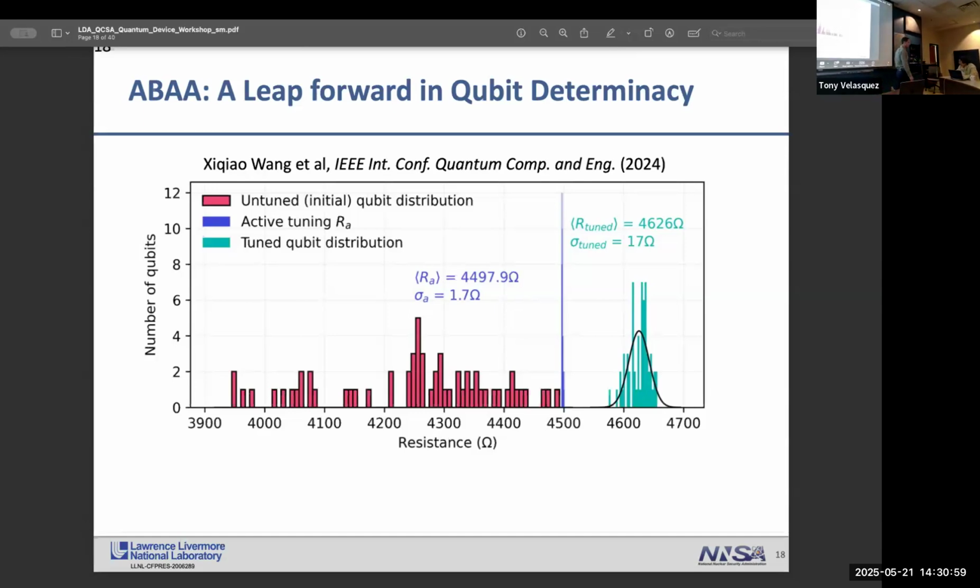For the etching, how selective is this etching? Is it like Bosch etch? I mean, this is an argon ion mill etch, so it's not a Bosch etch, which is a silicon etch.